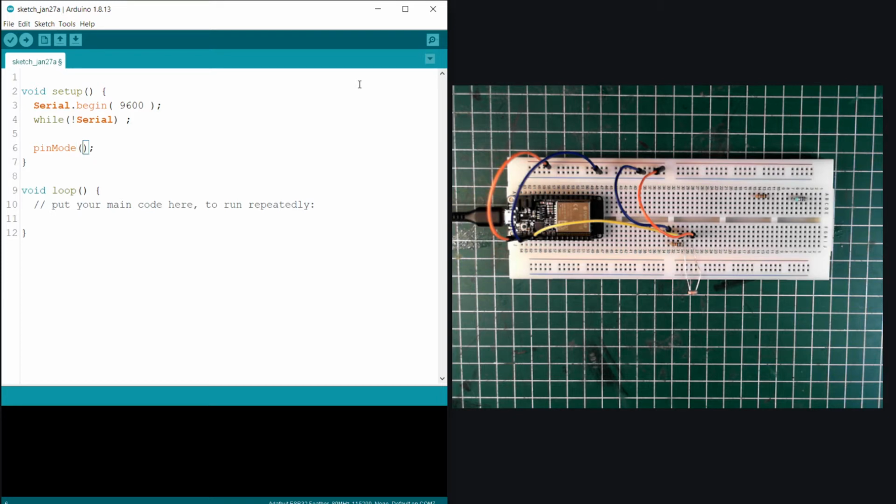Over here, these first two lines that I just did just establish communication back with my computer from the little board. And then we're going to tell the board, okay, I want this pin or this leg of the microcontroller to be an input, and for that I specify which leg I want, so pin A2, and this is going to be an input.